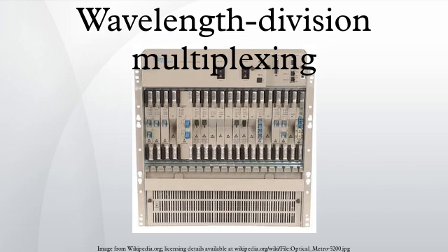However, recent standardization and better understanding of the dynamics of WDM systems have made WDM less expensive to deploy. Optical receivers, in contrast to laser sources, tend to be wideband devices. Therefore, the demultiplexer must provide the wavelength selectivity of the receiver in the WDM system. WDM systems are divided into different wavelength patterns: conventional, coarse and dense.